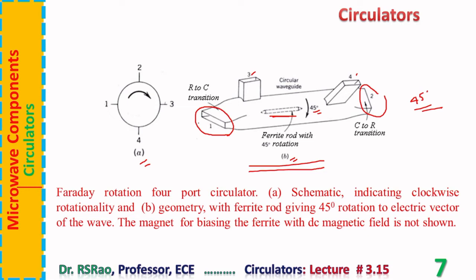We begin by considering a wave input at port 1. We also consider the input wave as one in the dominant mode. Now the wave enters, it travels like this. In the wave, the electric vector is vertical from one broader wall to another broader wall. While traveling, the wave comes across the arm with port 3, but it is unaffected by the presence of this side arm.